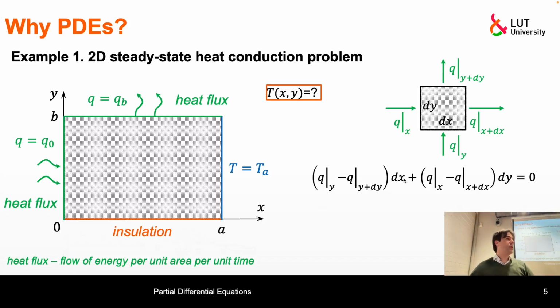Okay, so the general approach in how we do it in continuum mechanics, we take a very small element, we call it usually differential element of this structure. And since we are interested in a steady state problem, a steady state means that nothing changes with time, so it's something steady, something that's not changing in time. So it means that any piece of matter here inside this thing must be in equilibrium in terms of how much heat comes in, the same amount must come out.